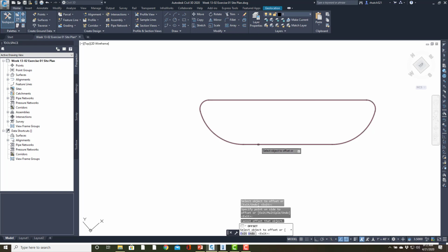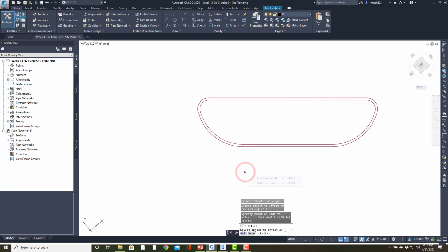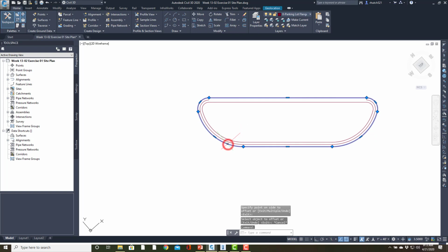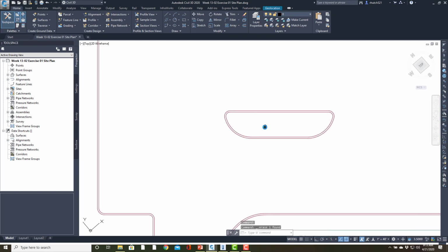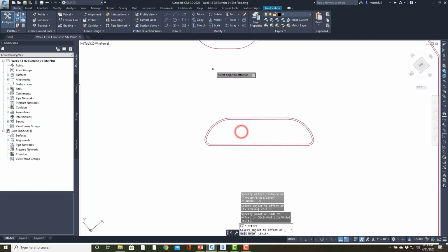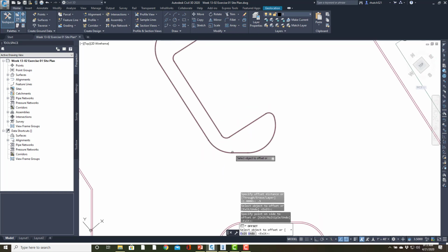I'm going to come over here. I'm going to offset out 1/2 foot. Hit escape. Go offset. Let's make it 1 foot. Click that outside barrier and go in, and lo and behold, it goes in. That is so bizarre. I don't know why it does it that way, but sometimes that's an easy fix because I'm sure it's something that's rounding off to the umpteenth decimal place that just isn't working well. But that's one of the ways that you can create those offsets.